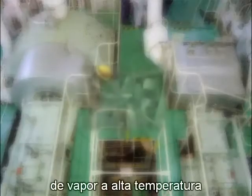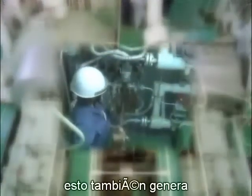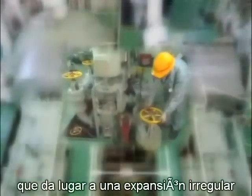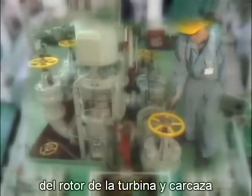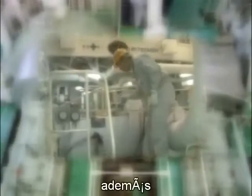Abrupt inflow of high-temperature steam into a cold steam turbine generates dangerous drain that can damage the turbine. It also generates excessive heat stress that gives rise to irregular expansion of the turbine rotor and casing, which can lead to serious accidents, such as contact between rotating and stationary sections of the turbine. Therefore, the entire turbine must be sufficiently warmed up before being put into operation.